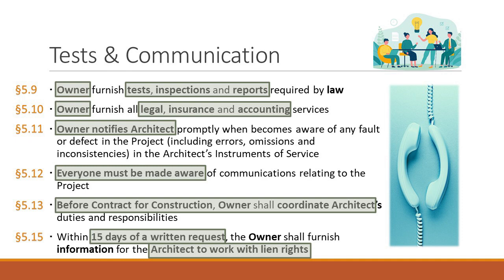In those projects, because it usually uses a mechanical process, a chemical process, or a combination of both, the contractor is obligated, when it's finished building this scrubber, to make sure the emissions from the smokestacks meet certain EPA standards. You test those at the end of the project, and if they're not meeting the standards, then the contractor's not finished and they have to do whatever tweaking to get the system to run properly.